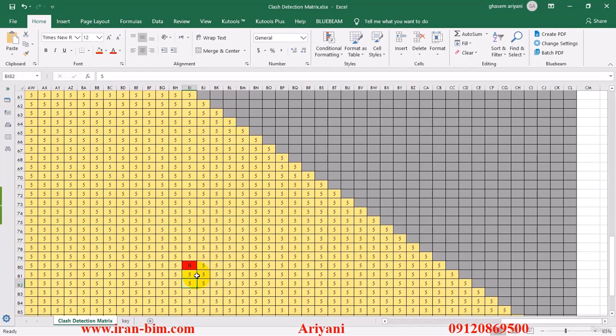And in the BEP that you do, you have to specify how the clash matrix will be done using these rule sets or not, so that all of the team members are familiar with the keywords and the colorings that you work for the clash matrix, so that there will be no confusion, and all of these need to be transparent and clear to everyone.